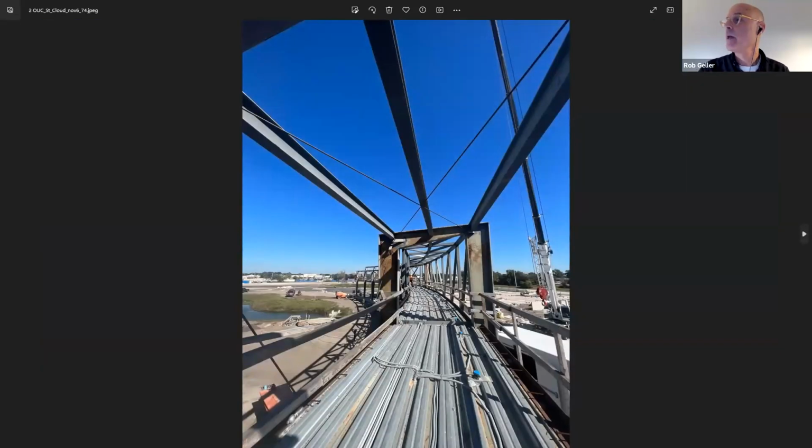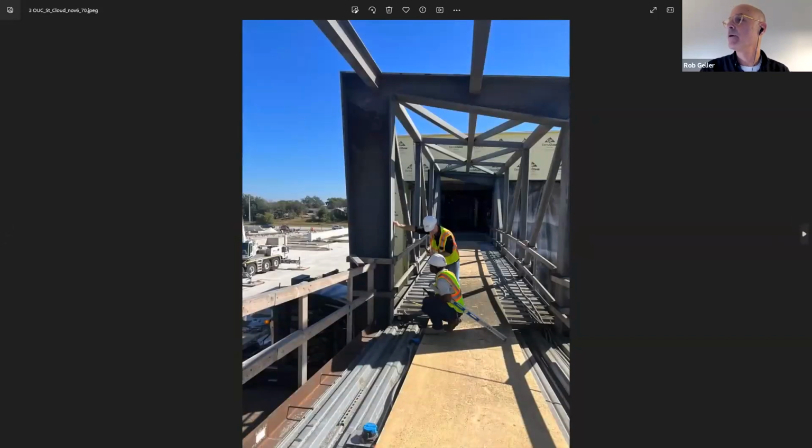Okay. So in the plans, this is sloped a bit for water runoff, and the plans say it's a 1 to 12 slope. Well, we went there just to get a sense of it and where everything could get bolted into, and it's actually 1 to 48. So we didn't have to change anything. What we were doing is pre-drilling holes in the posts to make it quicker and easier for them to do the installation. So that just confirmed how and where we need to pre-drill the holes.